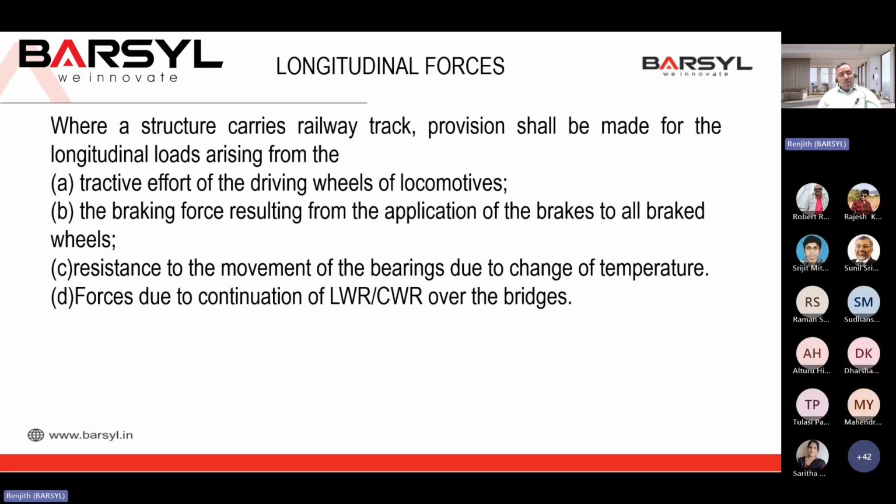Another longitudinal force is resistance to the movement of bearings due to change of temperature. So it is not 100% flexible. There is a resistance for the bearings, which also will produce a force on the structure. That also we have to take separately.